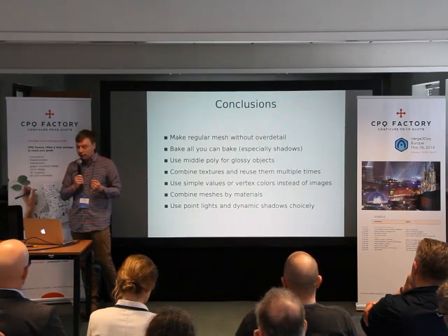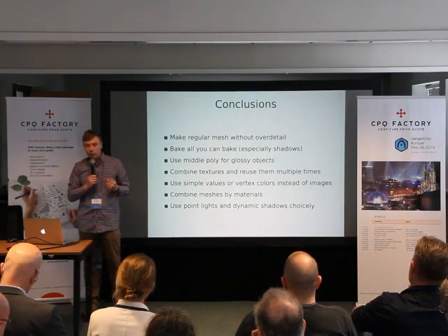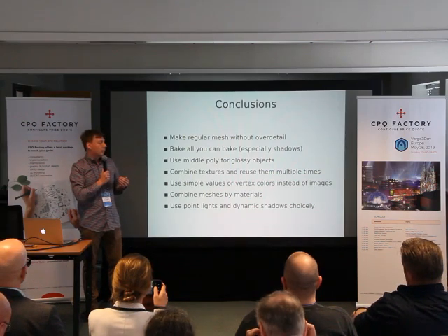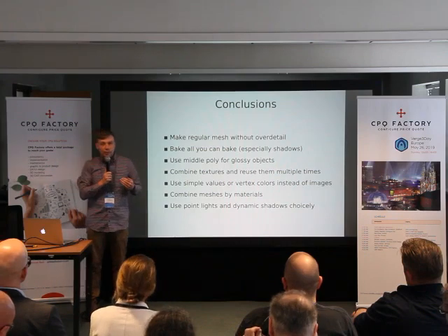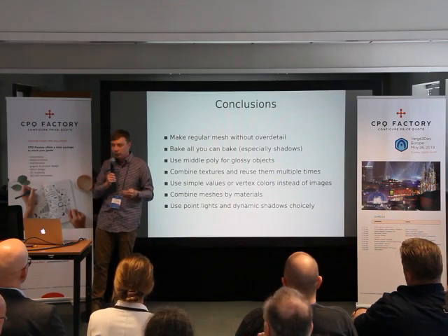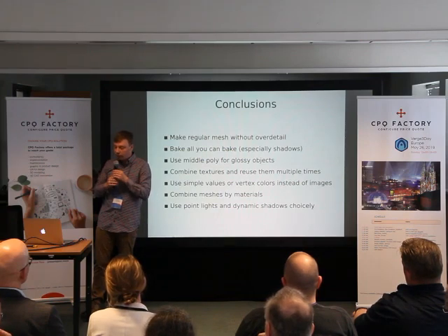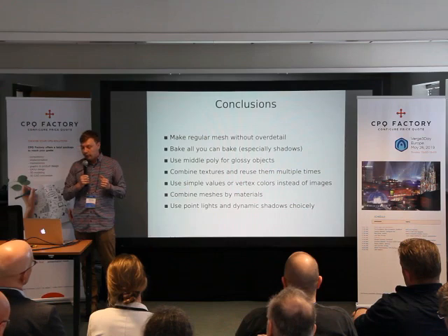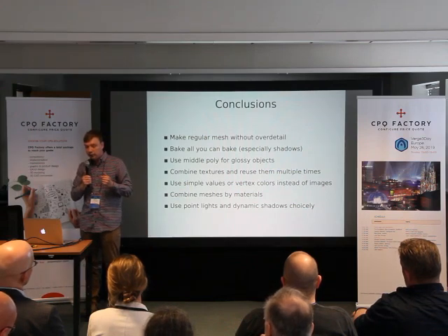Combine textures and reuse them multiple times. For example, if you have a noise pattern, you can use it in multiple materials multiple times by coloring it in different colors. And use simple values or vertex color instead of images.